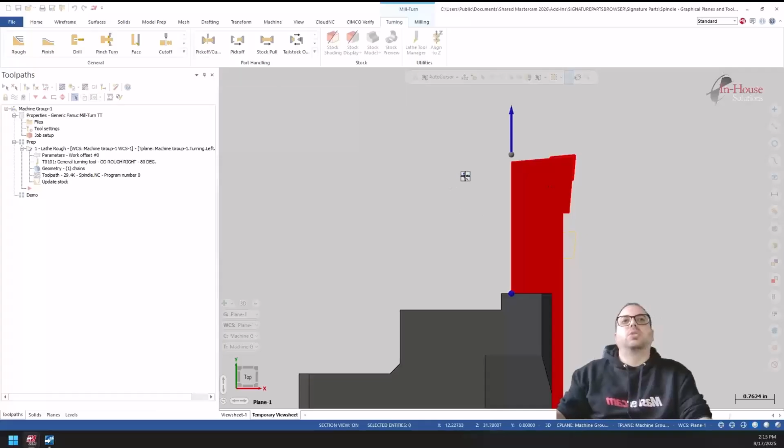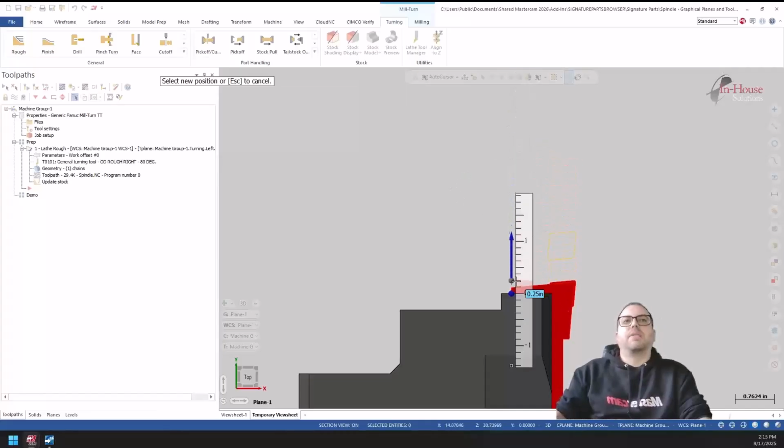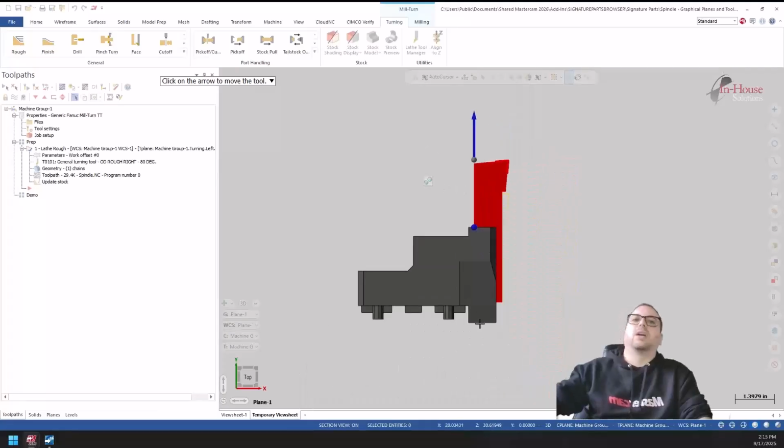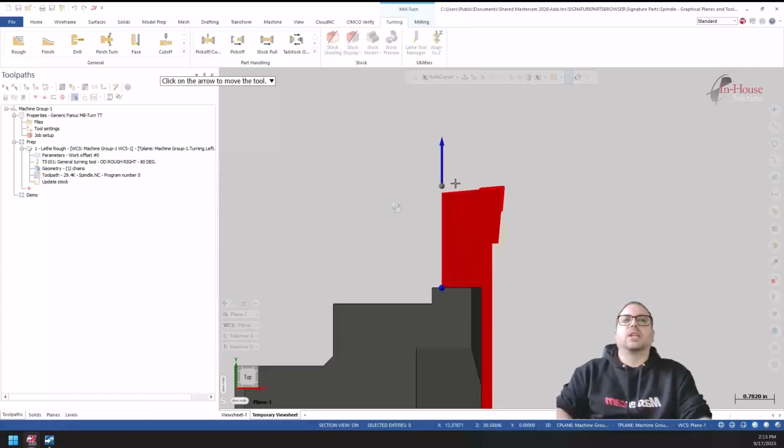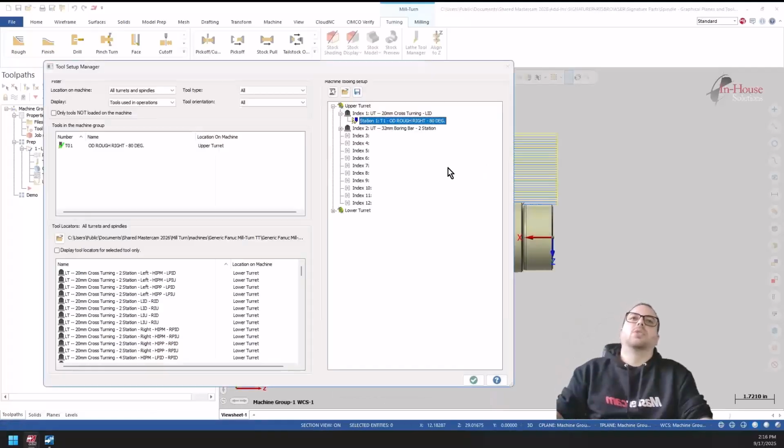So now when I go to this option here, my value is not relative to the back of the locator, but relative to the tip of the tool to the end or the start of the locator here, and I can set an exact value for this. This way I know what information to send out to the operator, and I can preemptively validate that the stick out of all my tools is good. So that's the new thing about tool projection in Mill-Turn.